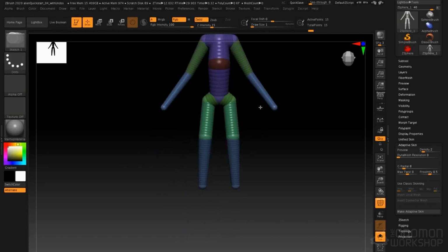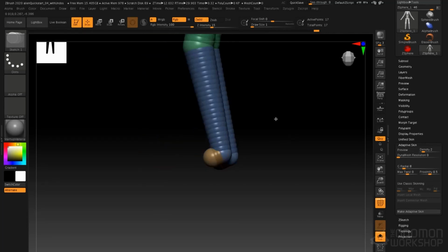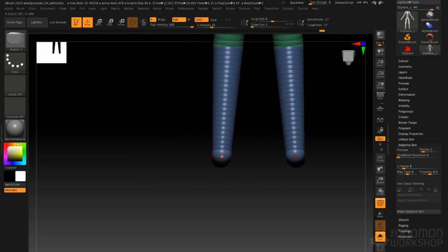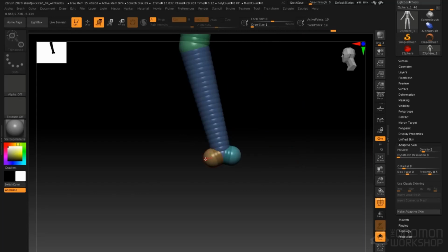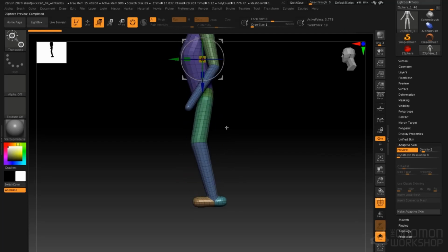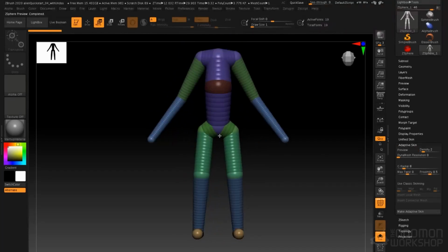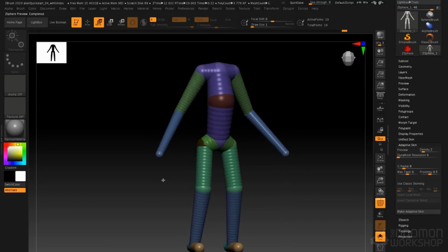So let's go ahead and add feet. We'll zoom into the ankles, go to Q for draw, start dragging to draw a child sphere and press the shift key to snap it, and then double click off the model. Rotate it around to the back and we'll add the heels the same way, snapping, and then double click off the model, and then use W for move to stretch those out to give the length of the foot. Press the A key to preview the mesh. Again, this is just your mesh preview. We'll press the A key once again to leave that preview.